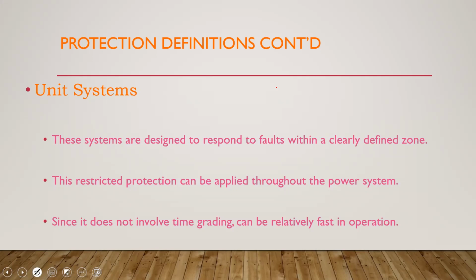We have voltage balance systems, differential. We apply it to some lines. But primarily, your differential would be applied to your transformers, your generators, etc. As I said, they do not coordinate with any other part of the system, but operate once there's a fault on the equipment being protected. As a result, operation is extremely fast.